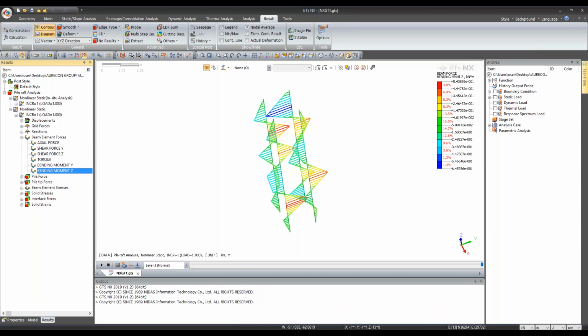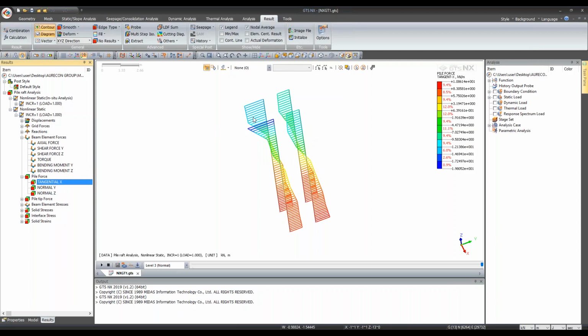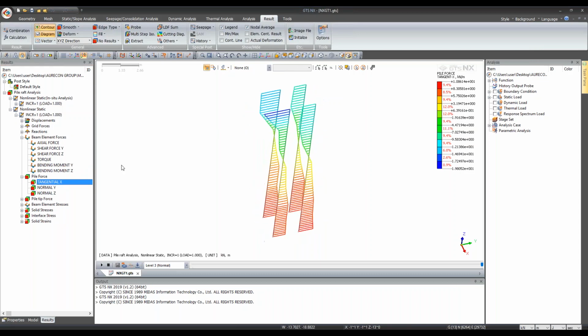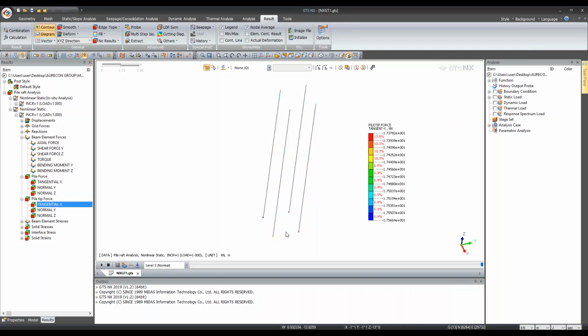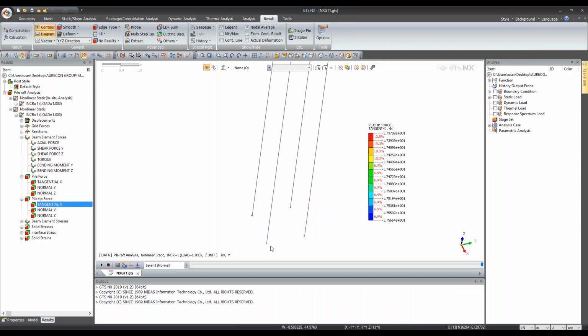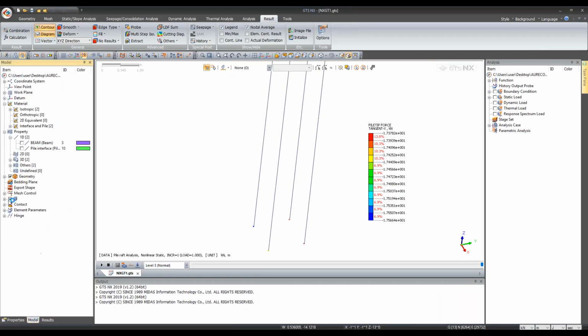And now I'm interested in skin friction, let's say. So I can find skin friction as such, and I'm interested in finding the pile tip force, which is nothing but end bearing resistance. Just double click here, you can find the values. Because these are at the very bottom, you can find the end bearing resistance. The maximum and minimum loads can be found based on the property of a soil present over there. You can find the end bearing resistance, and I'll be showing you the displacement contour now.